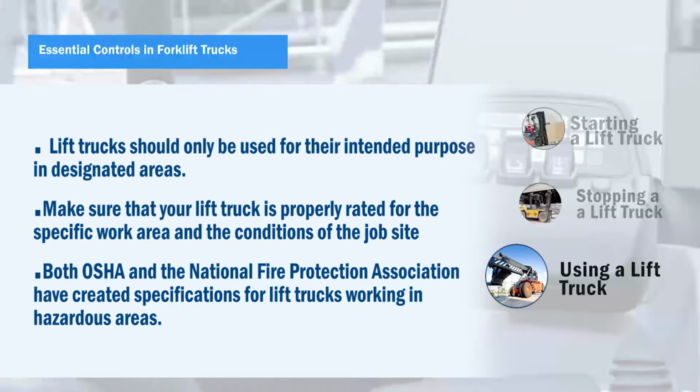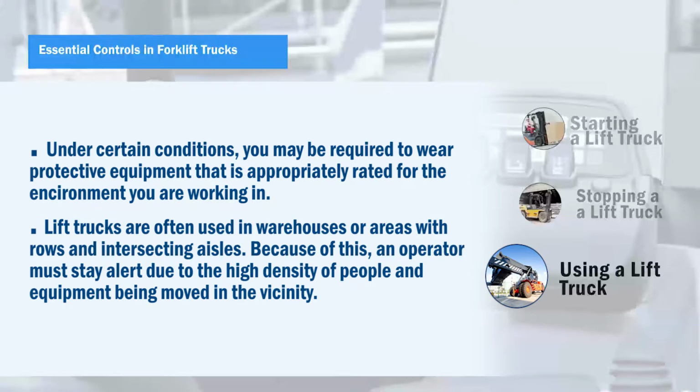Lift trucks should only be used for their intended purpose in designated areas. Make sure that your lift truck is properly rated for the specific work area and the conditions of the job site. Both OSHA and the National Fire Protection Association have created specifications for lift trucks working in hazardous areas. Under certain conditions, you may be required to wear protective equipment that is appropriately rated for the environment you are working in.